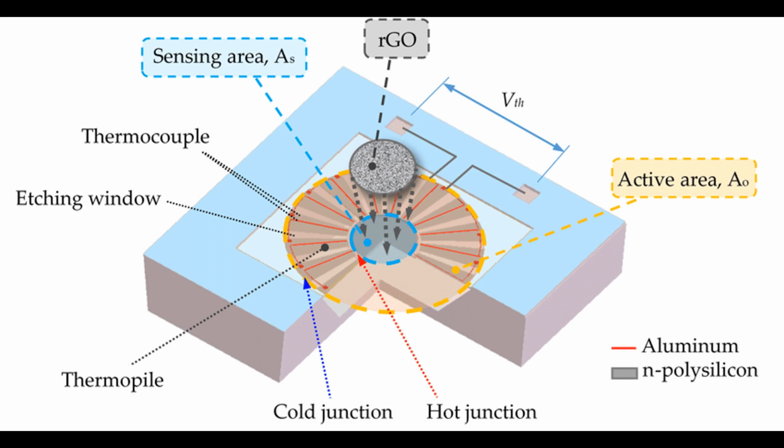Key points. MOSFETs operate as voltage control devices, with the gate voltage controlling the conductivity of the channel. NMOS transistors conduct when the gate voltage is higher than the threshold voltage, positive VGS, while PMOS transistors conduct when the gate voltage is lower than the threshold voltage, negative VGS.